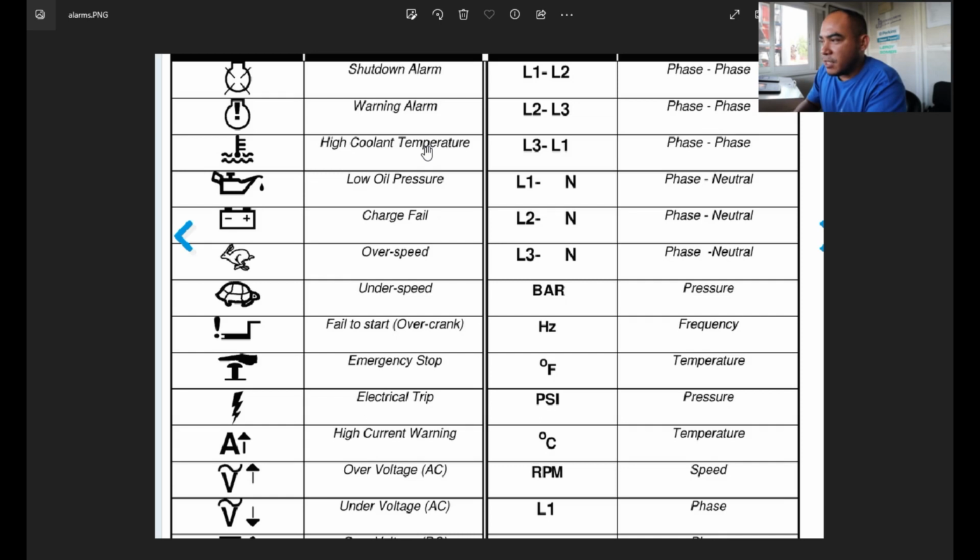Next, you also have to check the sensor to see if it is working correctly, by using the multimeter, and again by using your eyes, your visual inspection, for this type of alarm. Sometimes the issue is also loose wiring connections, so you have to check that too.